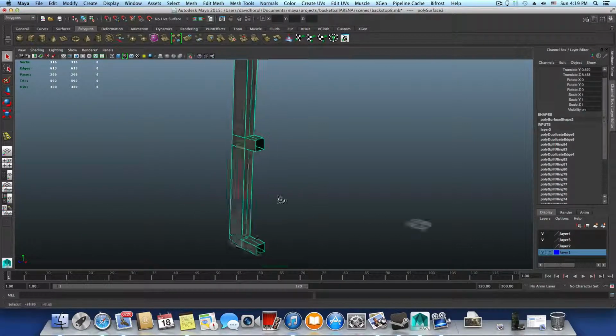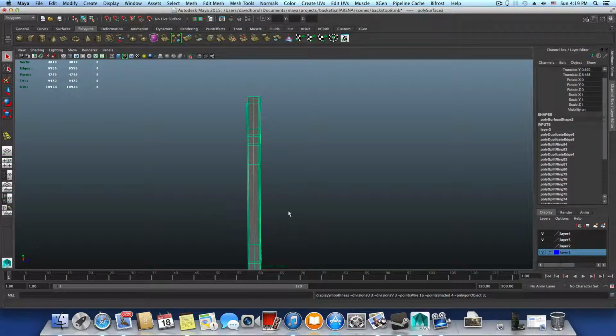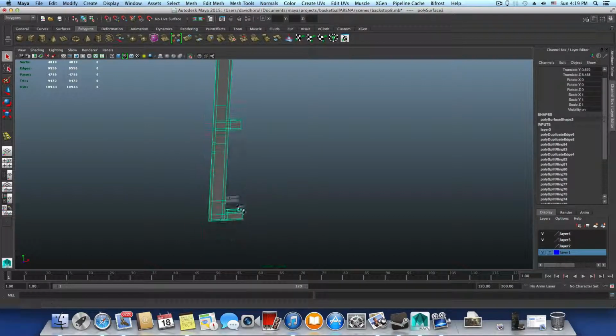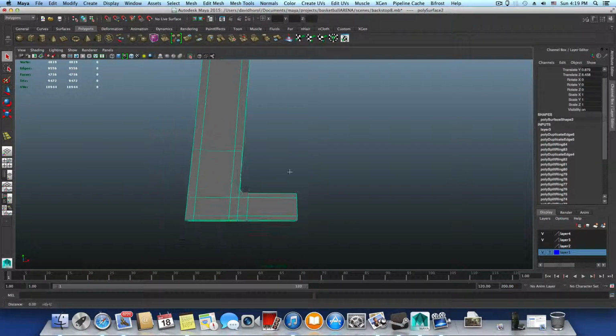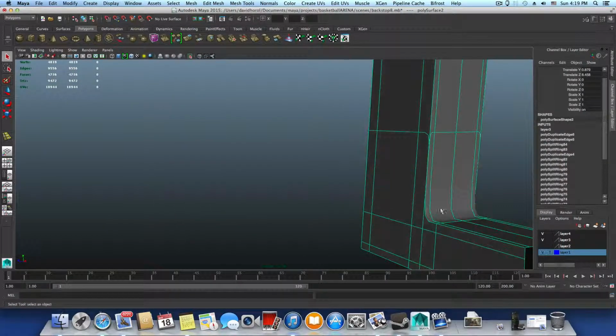Now we added all those edge loops for only one reason. This part of the body of this hoop, I want it to be smooth preview, or even just smooth. But to make sure it will be smooth but still look sharp, this is why we add all those supporting edge loops. So now if I press 3, I want to make sure that everything goes correctly as I thought, and that I have all those edge loops to maintain those sharp areas.